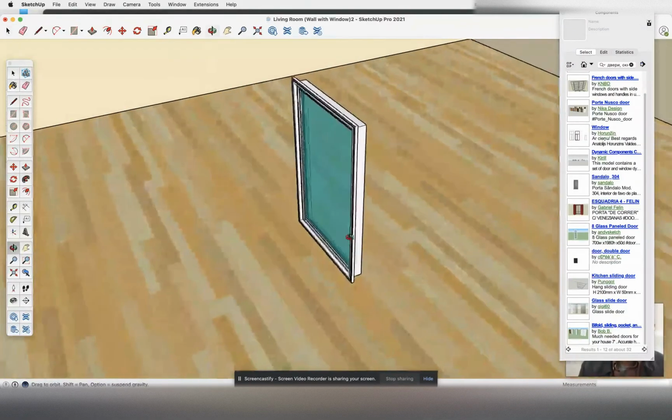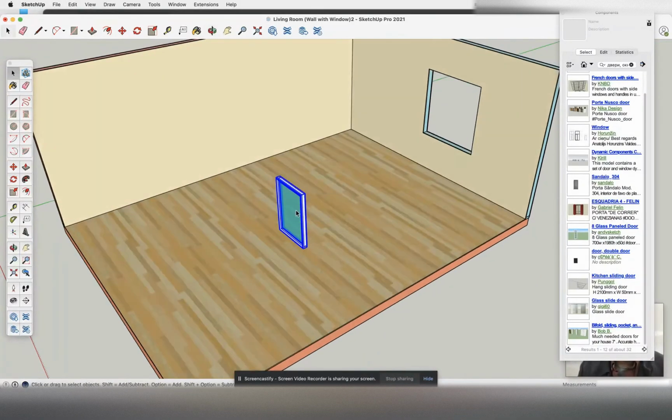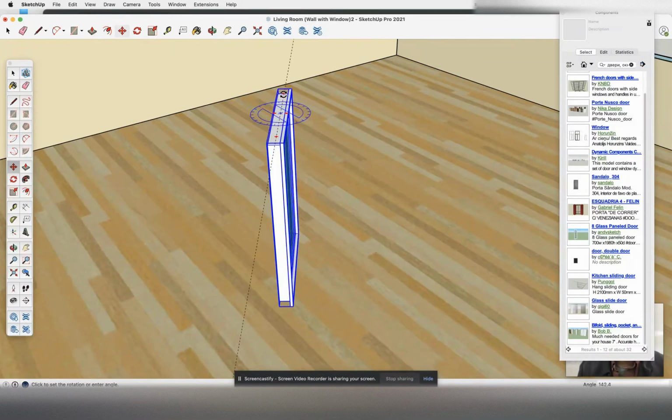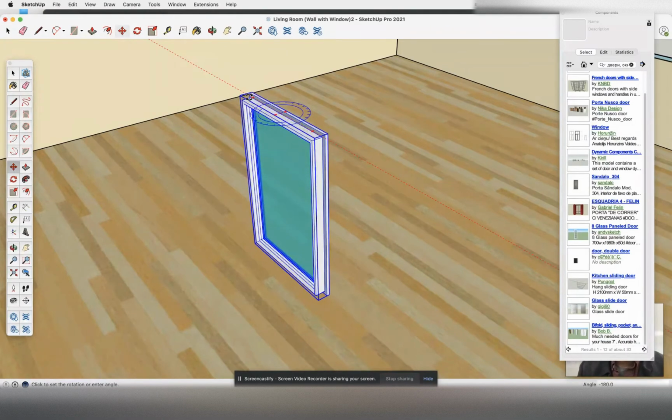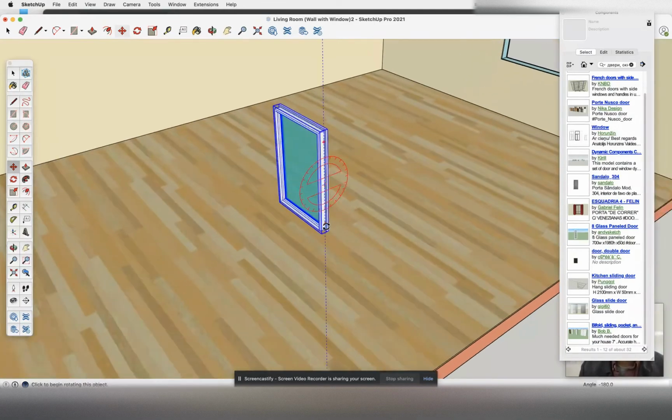In this case, if you want to rotate this window, let's just say it came in the wrong way, such as this one, I will select the object, press M for move, and you know how to do this before. You go and find the node on top, which allows you to create a compass. You click once, you rotate it 0, 90, 180, similarly to our last project in the past. Click it once, and it will rotate in the direction you want. Remember, 0, 90, 180. In this case, on the bottom right here is negative 180, and that's perfectly good.